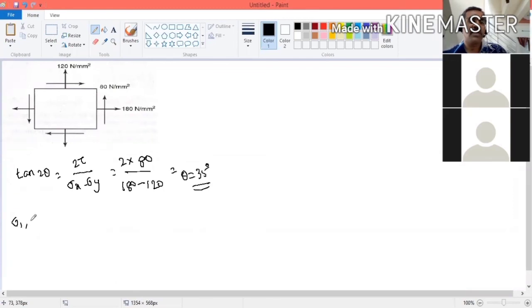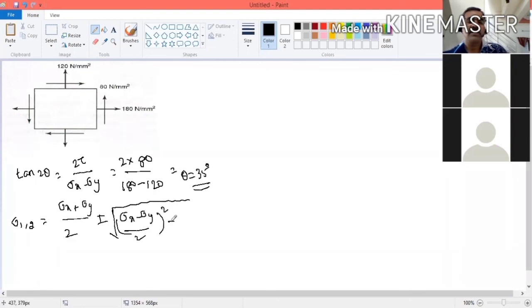Now you find sigma 1 and sigma 2. Sigma 1, 2 is equal to sigma x plus sigma y by 2 plus or minus root of sigma x minus sigma y by 2 the whole square plus tau square. This is the equation. What is the value of sigma x? 180.